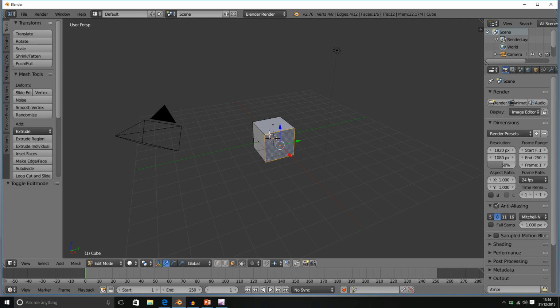Edges can be grabbed, can be rotated, but can only scale on a 2D axis. Vertices can be grabbed, cannot be rotated, and cannot be scaled. Let's see what I mean by this.